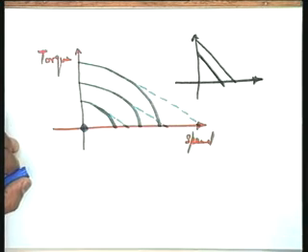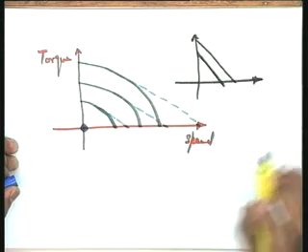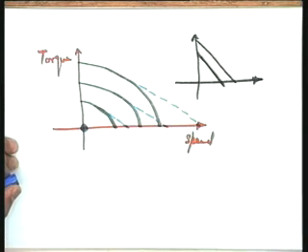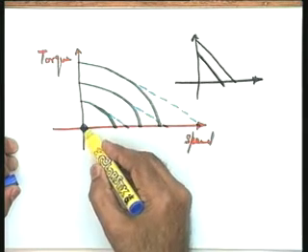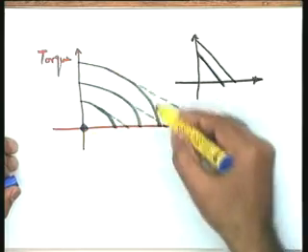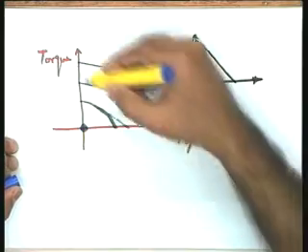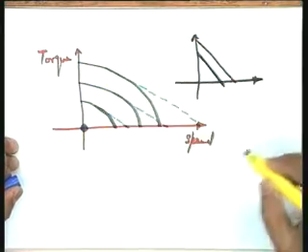That is, the actual position of the load is equal to the commanded position and the motor is not moving. And under equilibrium state, under the steady state, the motor is at standstill, and therefore speed is equal to 0. This is the equilibrium point of position control systems. And around this particular point, you see, even from the nonlinear characteristics, you have more or less linear region, and